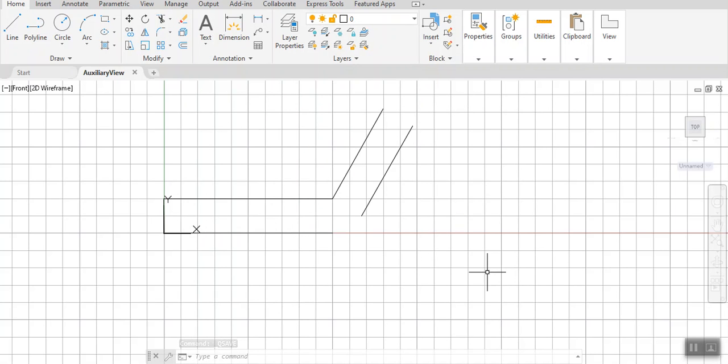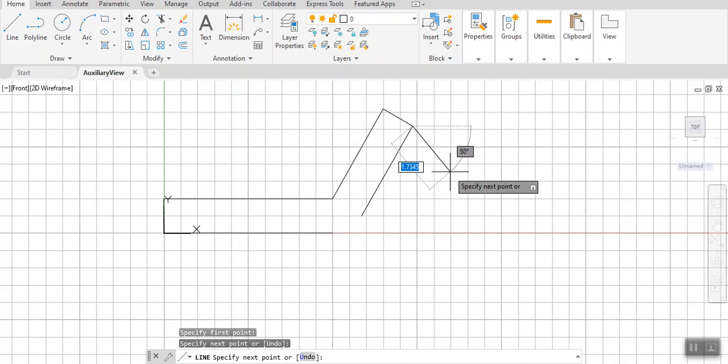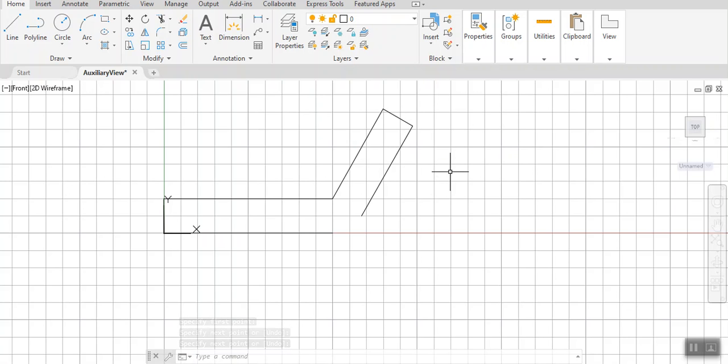One of the things I would like to do is draw a line between the two ends of the lines here. I already have one on the left, so I'm on the top. You click and click. And if ortho mode is on, the computer shows you when it sees the lines with a green square. Also, I'd like to use the fillet command to turn the bottom corner around, and the fillet radius is going to be 1 inch, I believe.